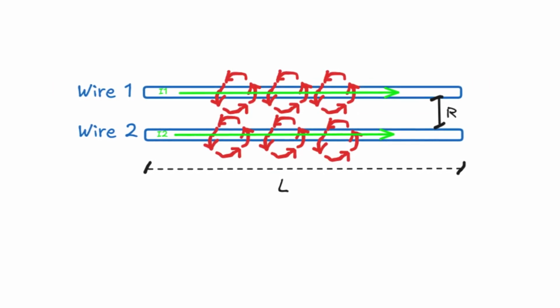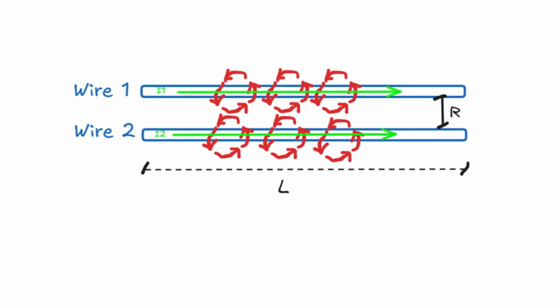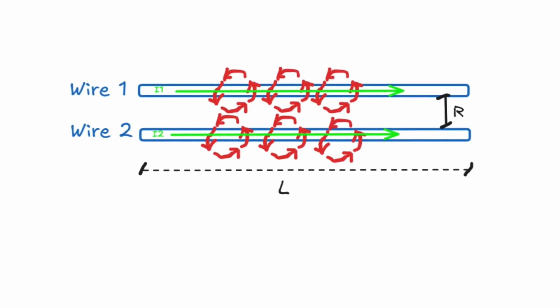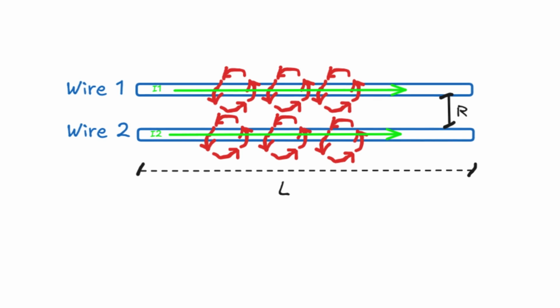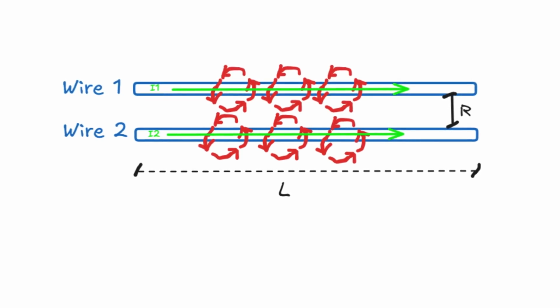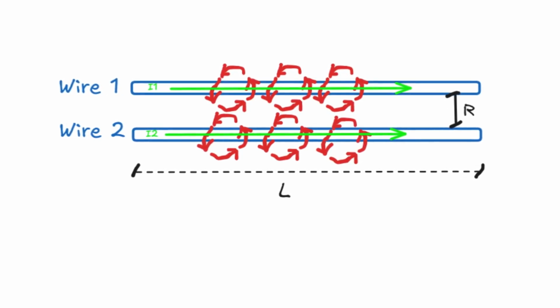Two-wire lines are even more visual. The energy isn't in the copper, it's in the space between the wires, air or insulation. That's why spacing, dielectric, and geometry change impedance.